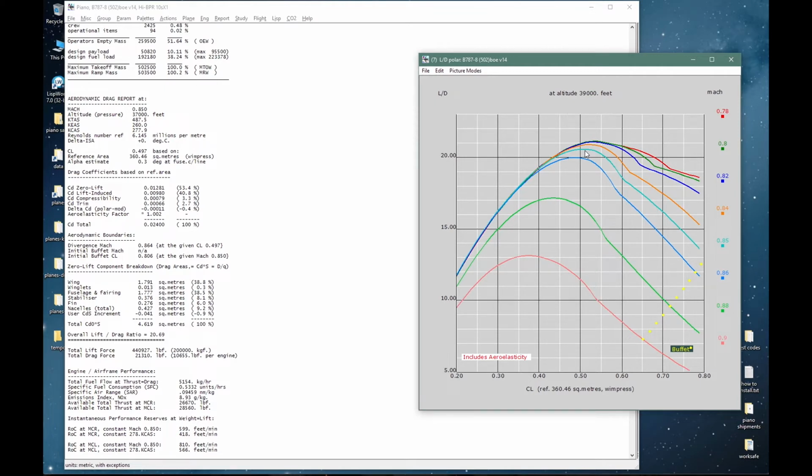To those of you that are aerodynamicists, if you are intrigued by the slight kinks over here, this is just an artifact of a simple aeroelasticity correction that is included in this case. We'll be talking about such details later on. The drag breakdowns are preliminary design estimates. Again, what matters to performance is the overall polar, which will include adjustments in each case.